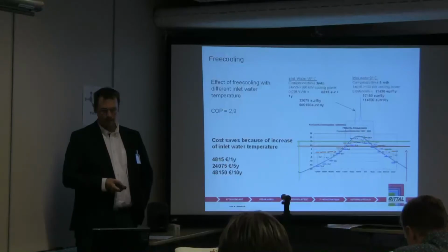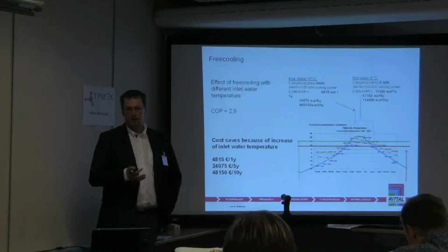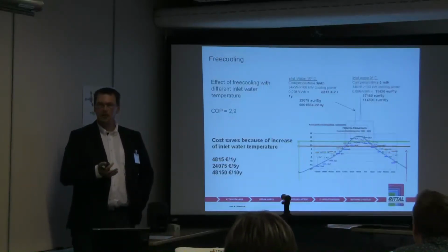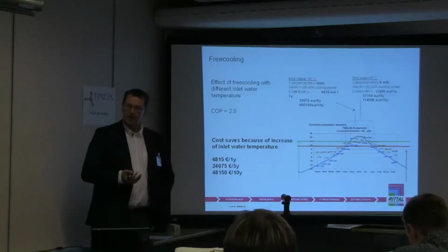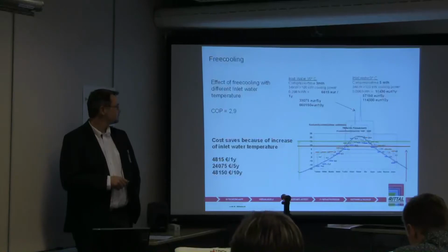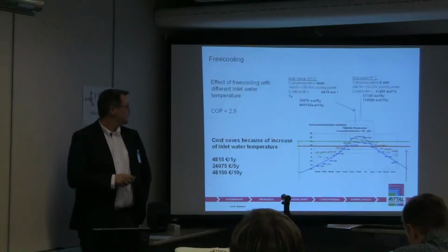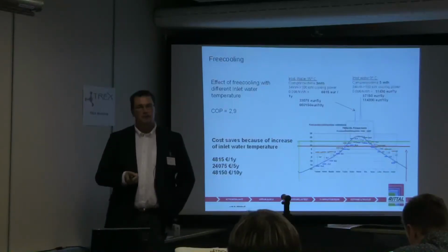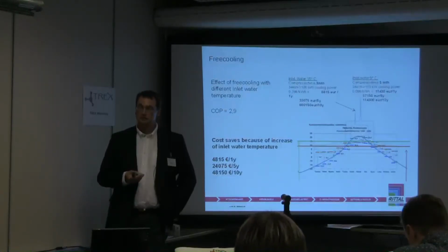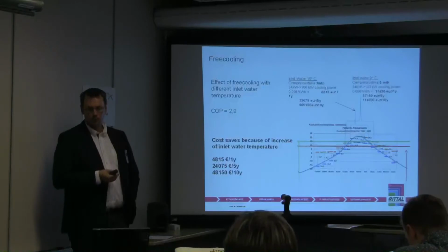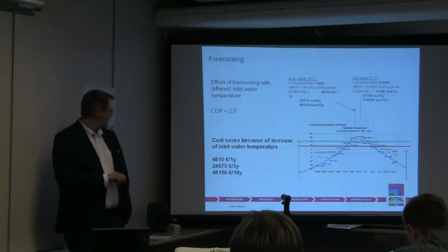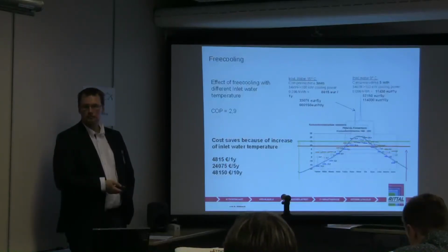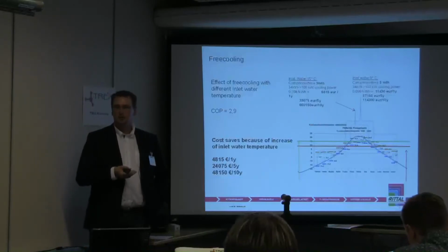But if we increase the inlet temperature by 6 degrees to 15 degrees, we can still set 22 degrees to the servers as an air temperature. The compressor time reduces to 3 months per year. We still have 100 kilowatt cooling power. We don't change anything else but the water temperature that we are running inside the data center. And now we are talking about the compressor time. We don't check the pumps. So the yearly cost, if we do that increase, is almost 5,000 euros. Only by raising the water temperature.